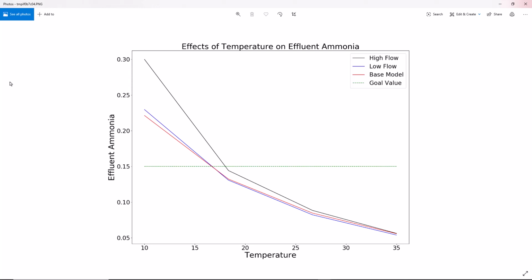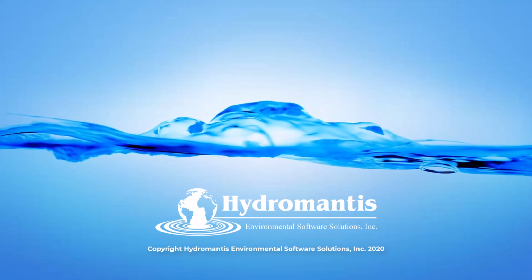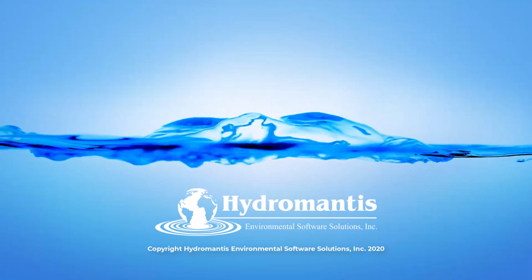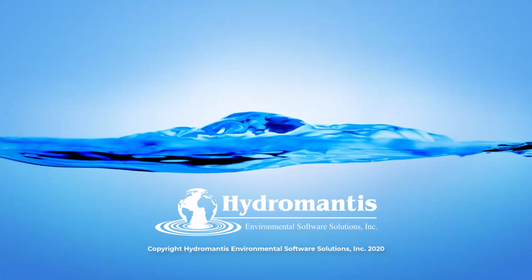By superimposing a target line, we can see that the low flow and base model scenarios meet the ammonia target at all operating temperatures above about 16 degrees Celsius, while the high flow scenario meets the target above about 19 degrees Celsius. You have now completed the 16th tutorial in the GPSX tutorial series. You should now be familiar with the 2 ways you can perform a multivariate sensitivity analysis within GPSX using Python.